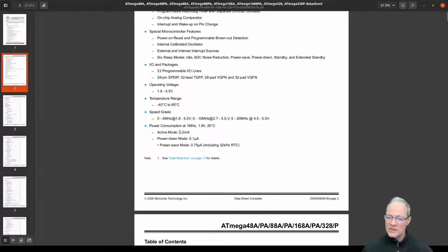Now this also seems to be an electrical engineering kind of thing, and it is, but you can also influence this with the way you write programs. For example, if your program does a busy wait, if it just loops all the time and tries to do something, that means that you're going to be all the time in the active mode. You're going to consume 0.2 milliamps here.